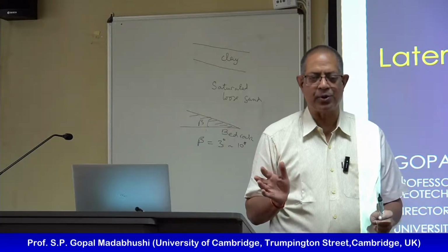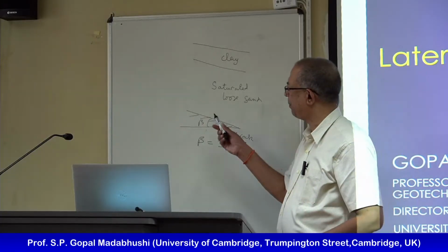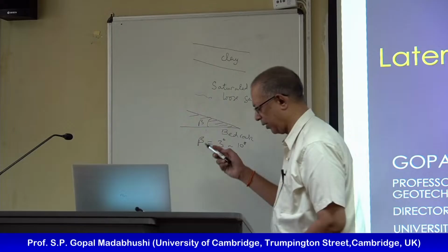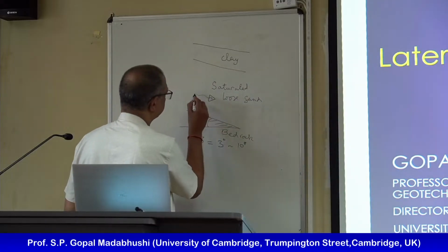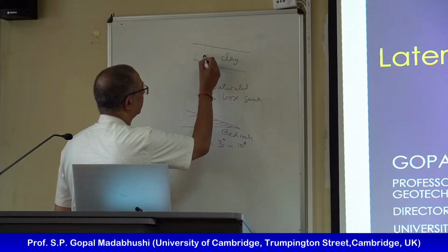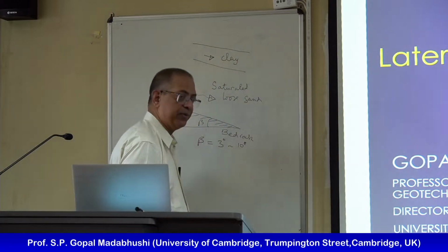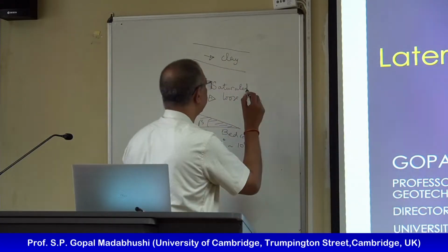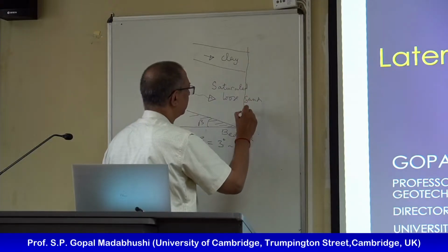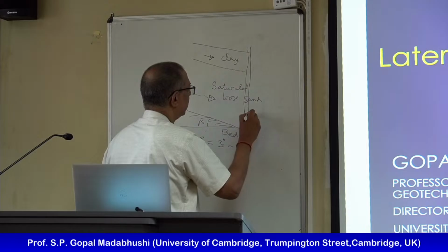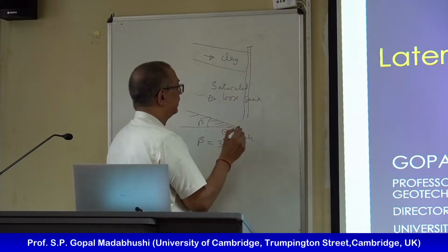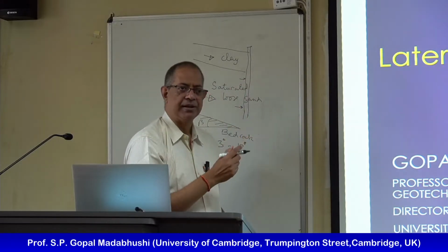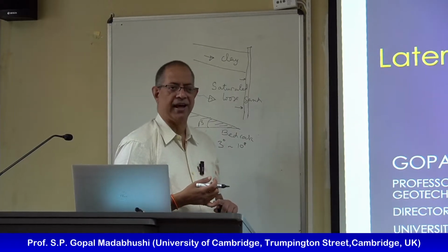So everybody thought it was all great, and then when the earthquake happened, obviously this stuff liquefied and moves along this direction, but as it does, the clay also goes for a ride with it. Now the problem is, if I then imagine I got a pile going through here, I'll get some amount of lateral pressure on this. That's the first problem. How do we estimate that?